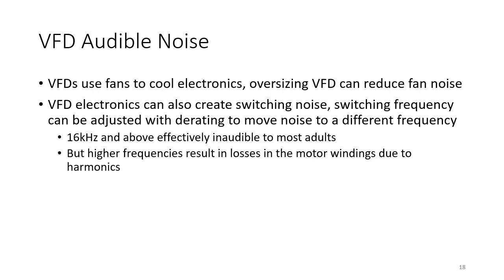So you may need to also derate the motor as well as derate the VFD to make sure that additional heat isn't causing any problems. But again, if noise is important, you've got those couple of options there: oversizing the VFD and switching the switching frequency, which often again means oversizing the VFD by derating.